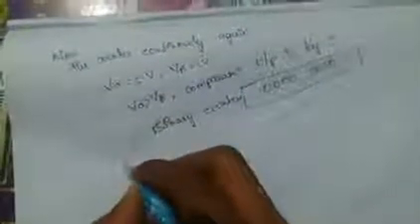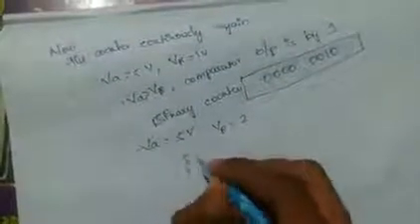Again the same process is repeated and the clock counts. VA is equal to 5 volts, VR is equal to 2 volts. Next, 5 against 3, 5 against 4. The process continues for several steps.